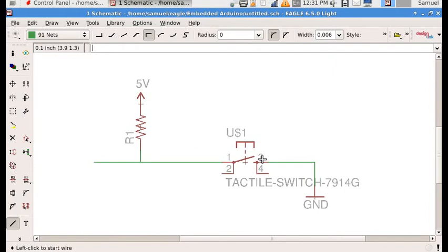So this button is inside of the joystick. You can actually see it if you look along the edges of the joystick. And whenever it's pressed, it goes to ground. So this would be pin 2. Whenever this button's pressed, it goes to ground. But you have this circuit right here, and usually these resistors are about 10K. But when we enabled that pull-up resistor, we made it so the transistors are arranged just so that there is a resistor between this line and 5 volts.